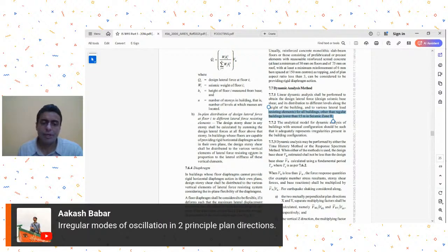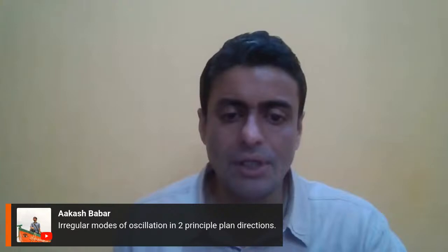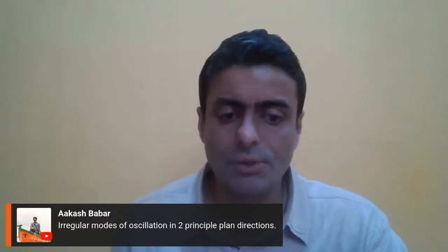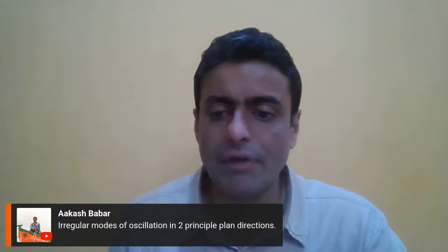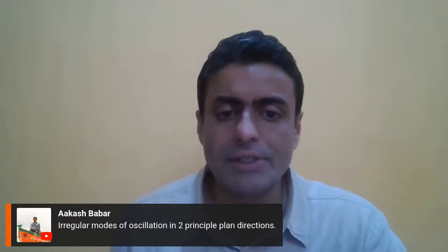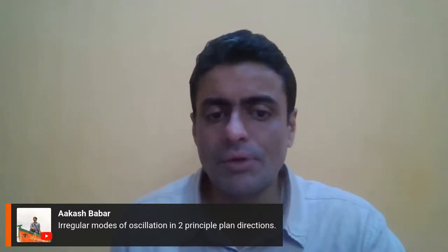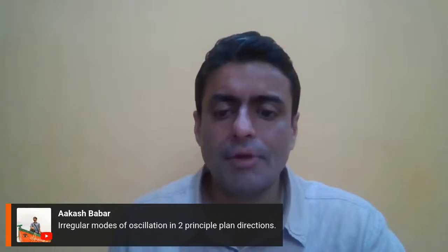and if you are getting some irregular modes, let's say you are doing a building which is in zone 2, but it is 10 meters and it is highly irregular. So anyway, if your model behavior does not show a behavior which is close to equivalent static, if you are failing as per table 5 and table 6 requirements, anyway you will again have to go to response spectrum. So you get my point?